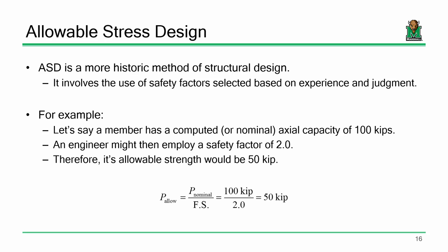Now, let's say that I am the manufacturer of this table. I'm the person that goes out and sells this table to consumers. Am I going to tell people that the maximum capacity of this table is 800 pounds? Probably not from a liability standpoint, because I don't want to tell people that, and then they go and start sitting and break it and hurt themselves. I'm not going to tell them that. So what I might tell them instead is that the maximum capacity is 400 pounds. That's the maximum allowable capacity or design capacity.